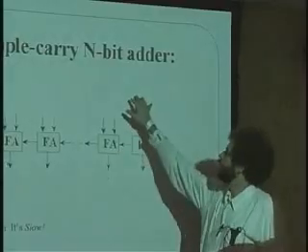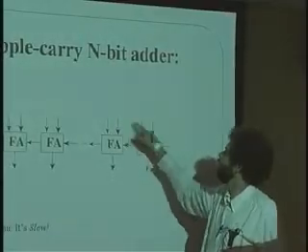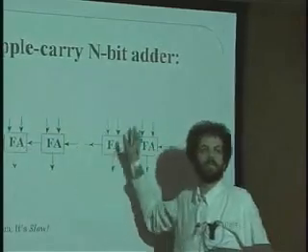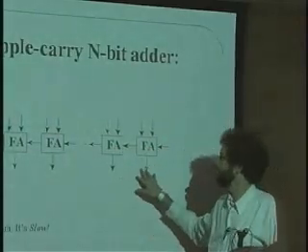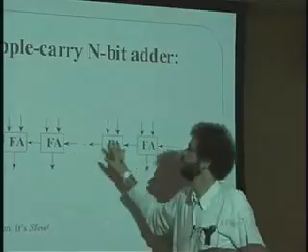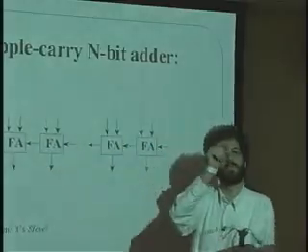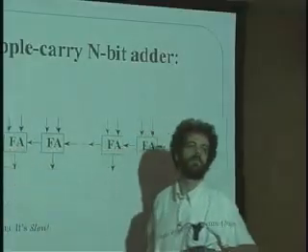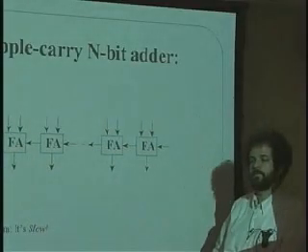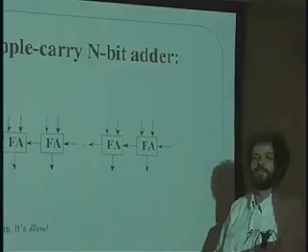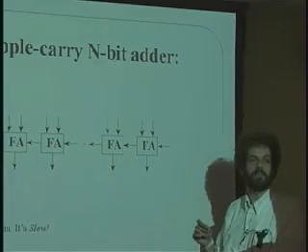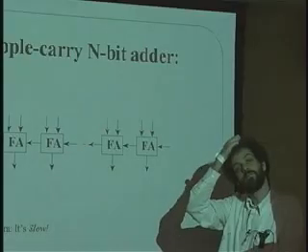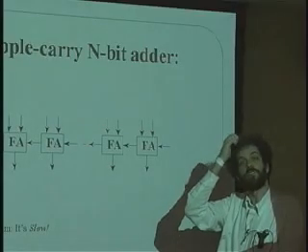And what would the carry out of the left-hand bit mean? So let's say I fed in 32 bits of A, 1, 2, all the way to 31 and 32, and also B, and I got a 32-bit number out of here, and I had 32 full adder 1-bit slices. Well, what would it mean for the carry out to be high? Isn't that going to depend on what our sign is? That's absolutely right. So if the numbers are positive and you get a carry out, what does it mean? The number got too big, right?